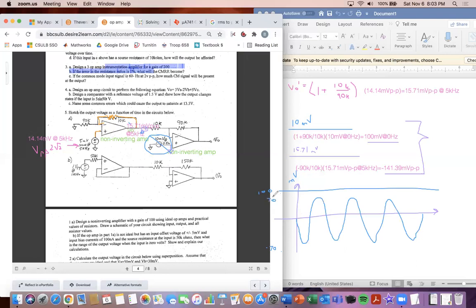And then we need to show the combination of these two. And so you're probably like, how in the world am I going to make a combination from this? It's not as bad as it seems because you just add the AC to this DC. So the DC one is the straight line and the AC one's the alternating current. So just add them together. So 100 minus 70, you'll see once it starts out, it's going to look something like this. So it's going to go down like to the 30 range. Then 100 plus 70 is going to go up to like the 170 range.